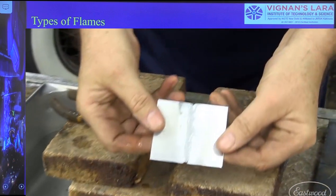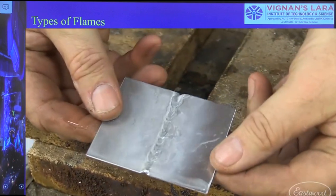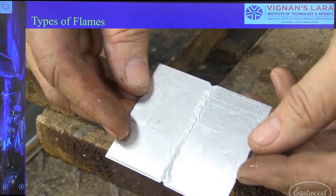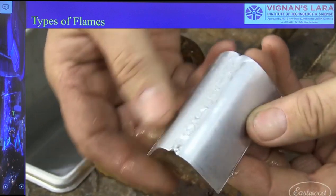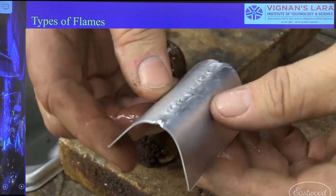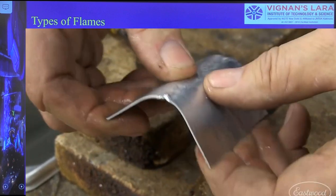Here's my welded side right here. Gives you a nice clean weld, 100% penetration to the backside, and the nice part about it has an annealing effect. Actually softens the metal. Now I can English wheel this out, I can hammer it, hammer weld it, bend it, shape it, any way we need to go.